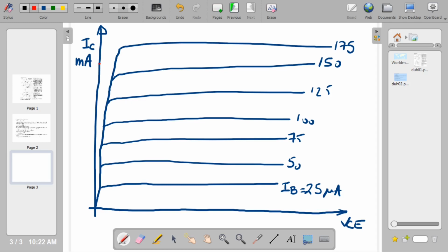Let's say it's over there. So maximum collector current at saturation. So that's one point. You need another point. And the other point, you get it by setting IC equals 0, which corresponds to cutoff. And that gives you the maximum VCE. So let's say it's here. Okay, so this is saturation, and this is cutoff. And now you draw that line, or you try to draw it.